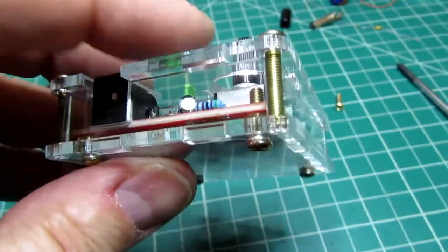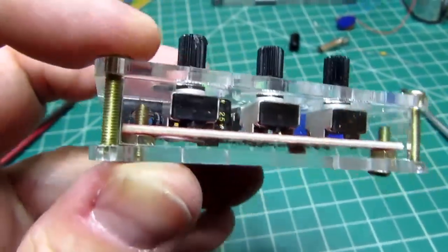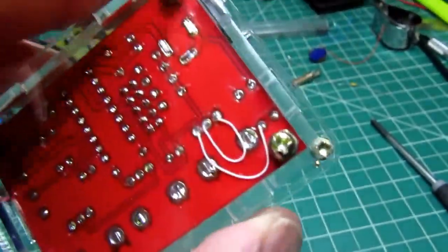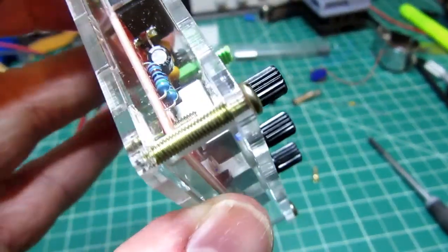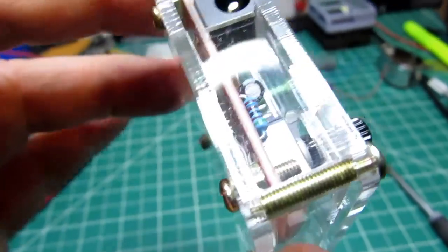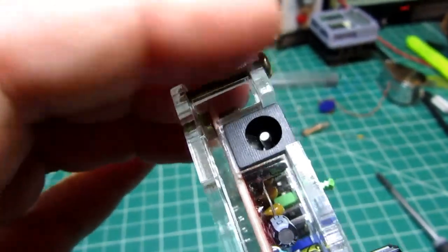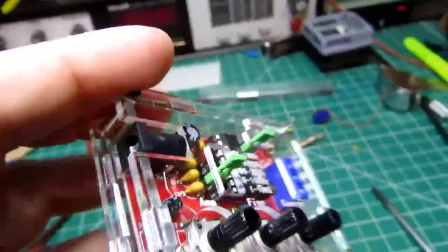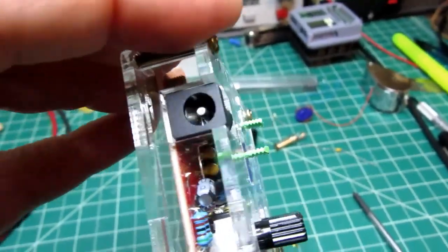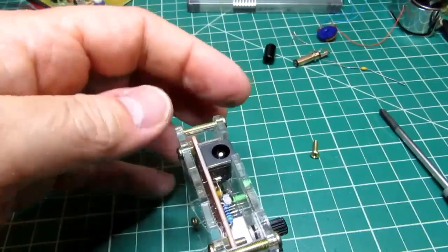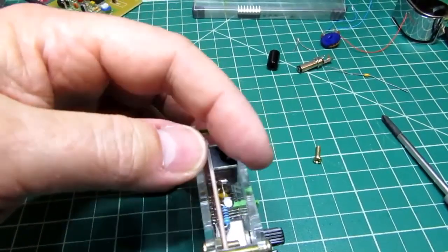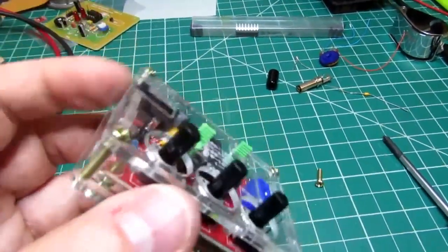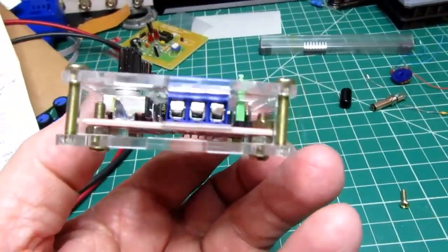It's a bit of a trick to figure out how tight to make these 4-corner screws. They go in pretty stiff because they're cutting their way into the plastic on the bottom. And it would be pretty easy to over crank them and probably break off the tabs or bust out the hole or something if you over tighten them. So I was just cranking down a little bit at a time and testing for looseness between the top and the bottom, just trying to, you know, wiggle them a little bit with my fingers until it felt like it was just tight but not tighter. And then I called it quits as far as tightening each screw that way.